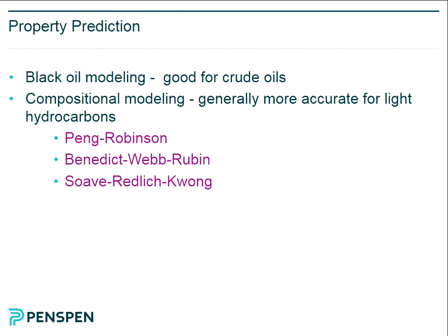So for single phase flow, I'd certainly recommend the Moody chart, which I've shown you. Whether it's for gas or liquid, it's equally valid. But there are a whole bunch of these equations that you'll see referenced, particularly from American publications: Panhandle A, Panhandle B. Panhandle refers to part of Texas. These are pretty old-fashioned now. Actually, they're not typically used. Pretty much all hydraulic analysis I've ever done has been based on some kind of program, or Darcy-Weisbach, Colebrook-White, not using these correlations.